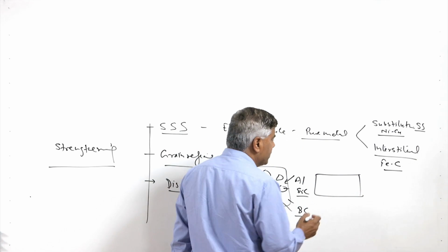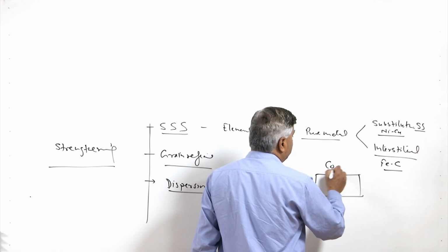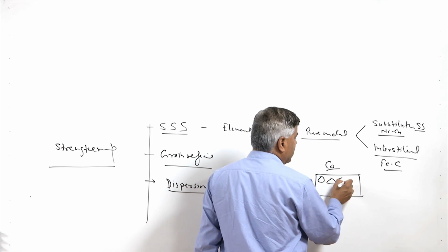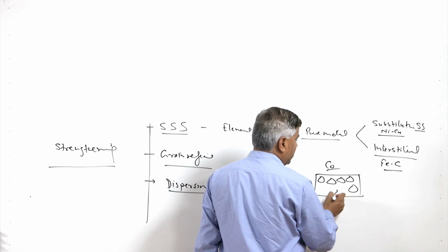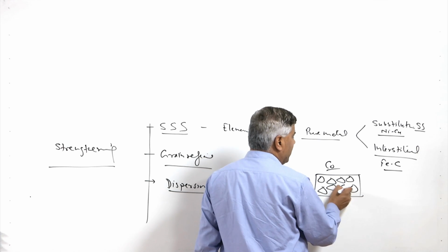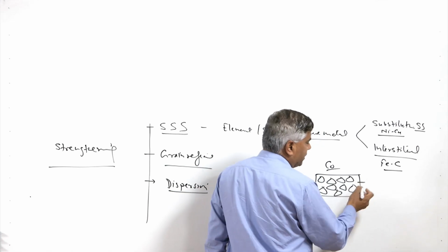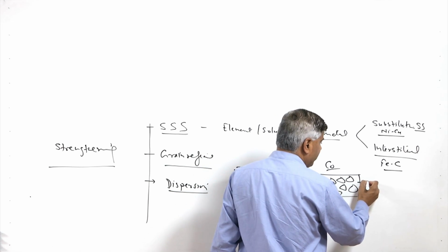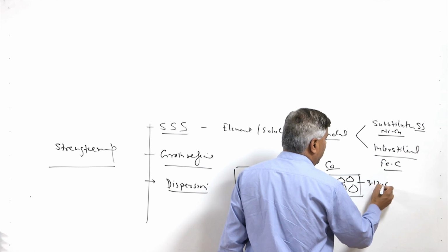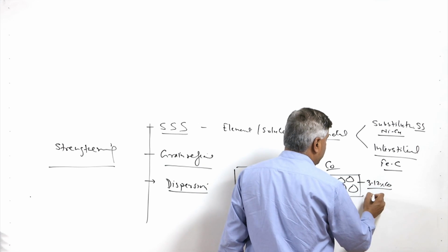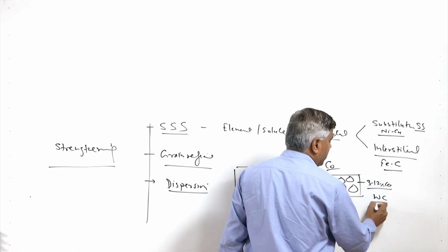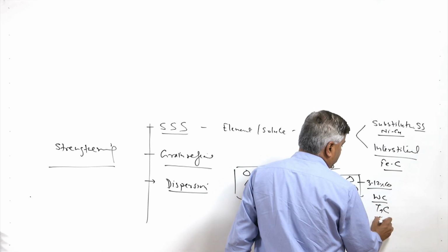Carbide tools are one of the examples wherein a cobalt matrix is fitted with carbide particles of tungsten, titanium or tantalum. The proportion in carbide tools may be about 3 to 12% cobalt, with the remaining being tungsten carbide, tantalum carbide or titanium carbide.